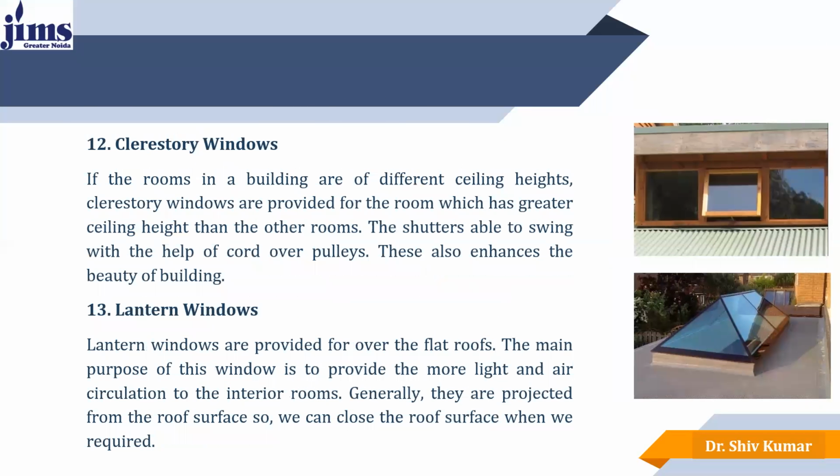The next is clerestory windows. If the rooms in a building have different ceiling heights, then clerestory windows are provided in the room which has greater ceiling height than the other room. The shutter is able to swing with the help of cord over pulleys. These also enhance the beauty of the building. Here you can see in the first image the clerestory windows. These are also called ventilators.